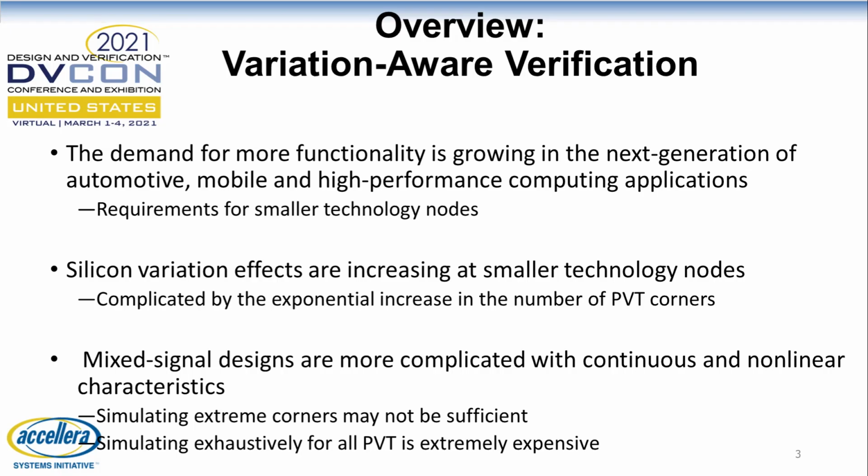However, in analog and mixed signal designs, circuit behaviors are more complicated. One has to consider the continuous and nonlinear nature of analog signals. Consequently, checking designs on a limited number of corner simulations may not be sufficient in AMS verification. On the other hand, simulating and checking AMS designs exhaustively in a continuous PVT space is neither scalable nor practical, since the cost of simulation for complex AMS designs can be too expensive.